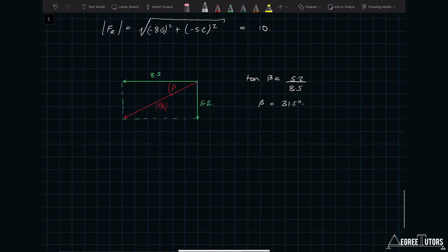We've got to now just sum up all of the moment effects of all of those individual forces to work out the combined effect. So we'll say the sum of the moments is equal to, and again, we're just counting up the moments we've already evaluated. That gets us 546.2 Newton meters. Again, a positive number indicates that the resultant moment is a clockwise moment.